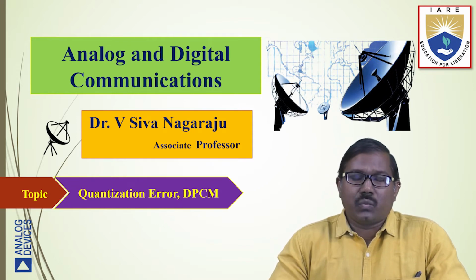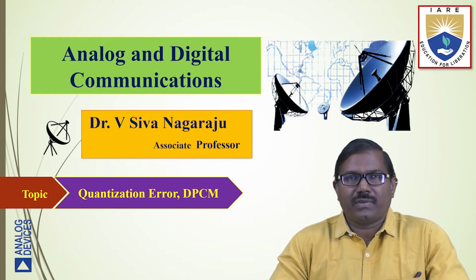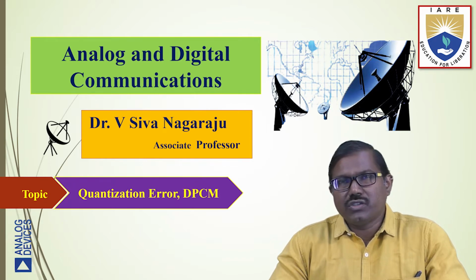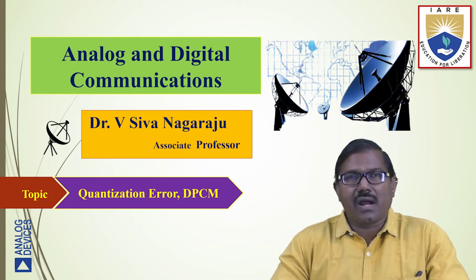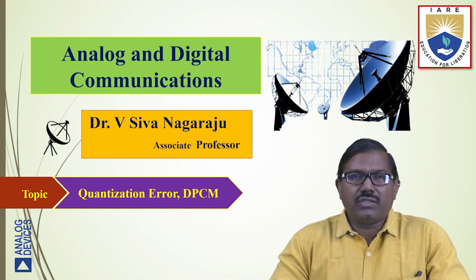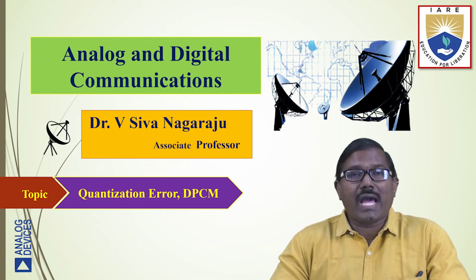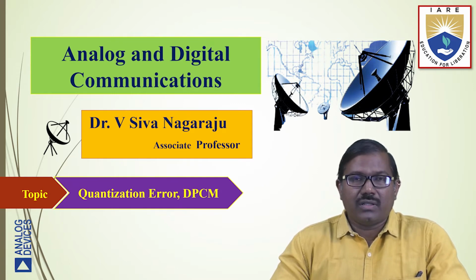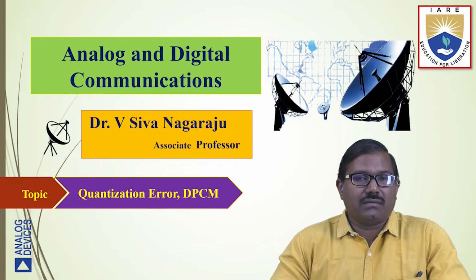In the last sessions, we discussed how to convert an analog signal into a digital one. Those operations were elaborately discussed in PCM. In PCM, we have three important blocks: sampler, quantizer and encoder. The sampler converts the continuous time domain into discrete time domain, whereas the quantizer converts continuous amplitude into discrete amplitude. When the conversion is going on, an error occurs. That error is called quantization error.